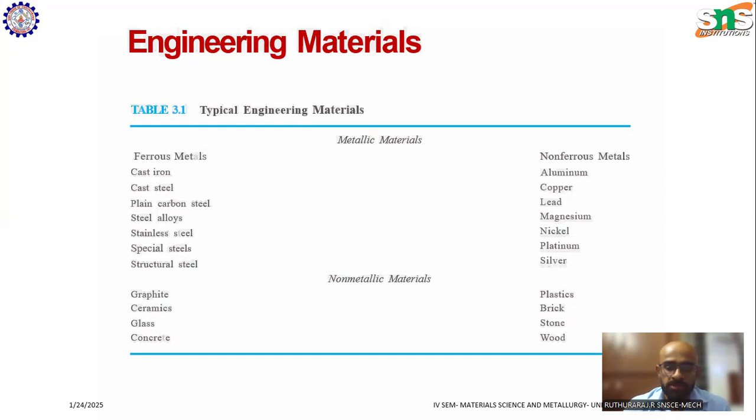There are two types of deformation. As I said, you are stretching the rubber band. The load which we are applying is called a tensile load because we are stretching, pulling it. Whenever a load is applied and the object is pulled, it is called a tensile load. When you compress a spring, it is called a compressive load. When you apply a tensile load, the rubber band stretches, and when you release the load, the rubber band returns to its original shape.